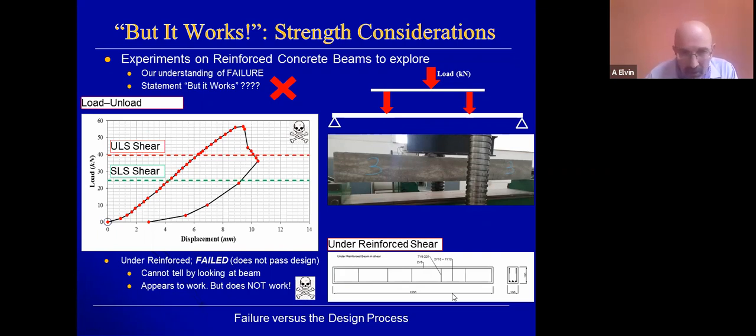This is under-reinforced. This beam is under-reinforcing shear. Number 3 was under-reinforcing shear. Here are the shear links. This is the spacing. Tensile reinforcement, good. Compressive reinforcement, good. Shear links spaced at 225 millimeters violate the code. But there's enough steel in the shear links to satisfy the code. So it satisfies the shear link requirement, but does not satisfy the spacing requirement.